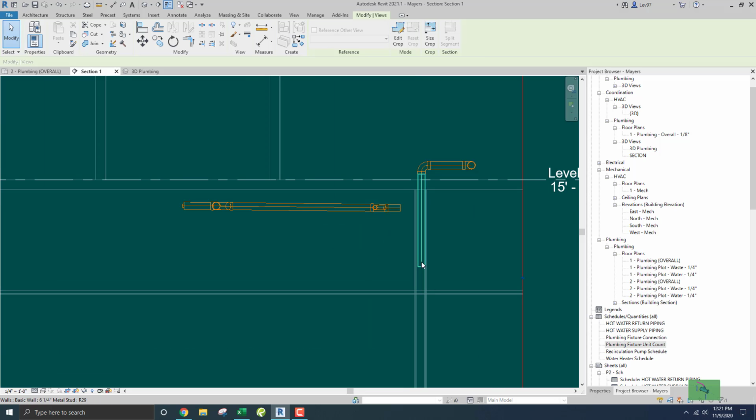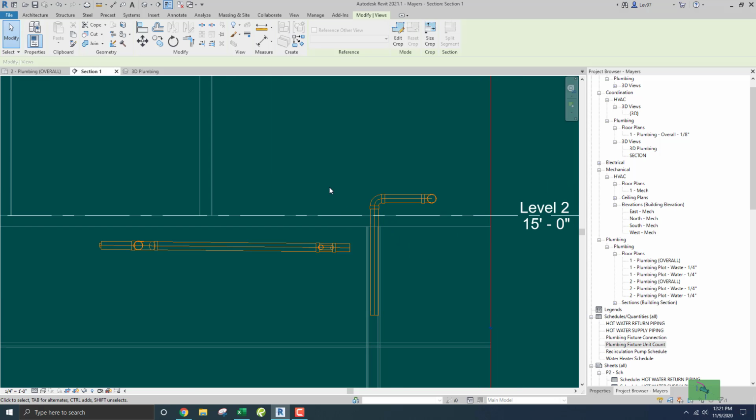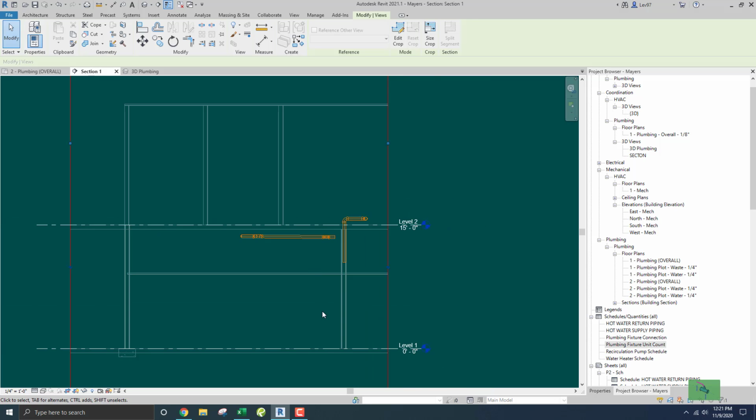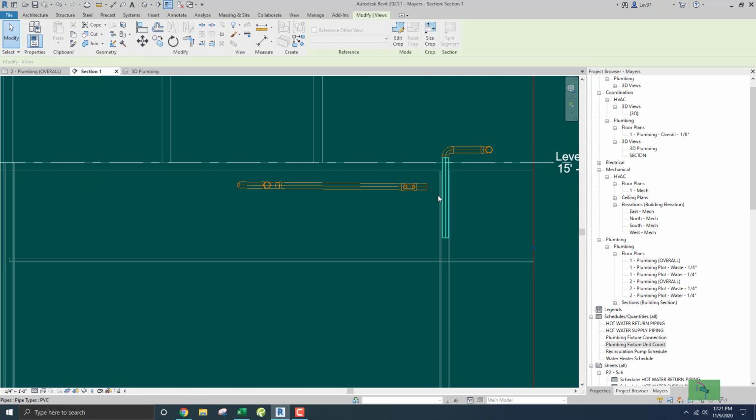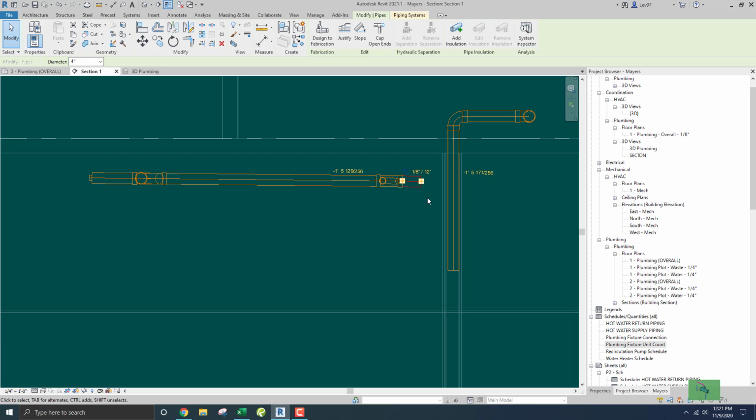So my vertical is in the floor, it's in the ceiling space. So I have to have my wall, a full height wall going through the ceiling and up to the floor, because I'm using that as a cavity to go down through the first floor to the foundation, so that we can collect everything under the slab, right? So back to this guy.